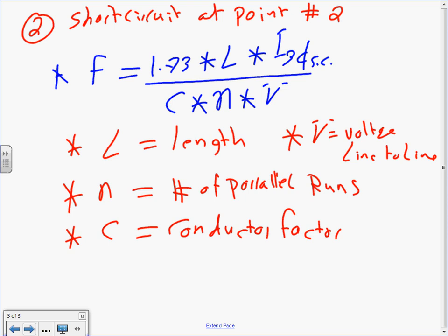Any question about this F factor? It's a factor. Why F factor? Cool. Now, why do we care about this one? We care about it because that's the percentage that you're going to cut the short circuit by that's coming from the transformer to your building. Any questions about this?